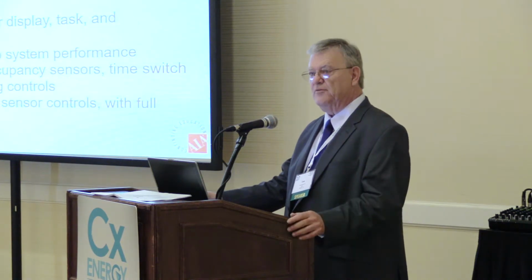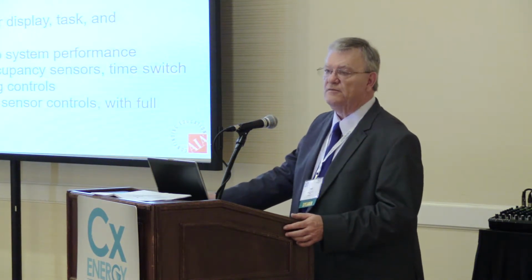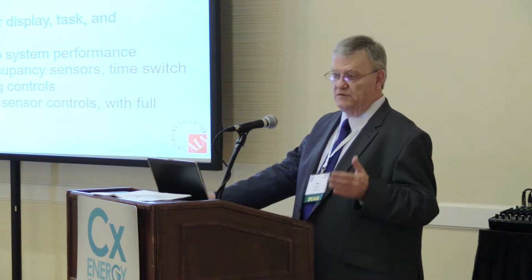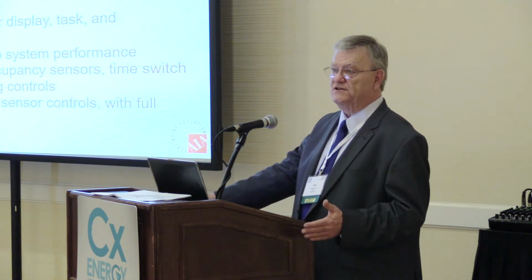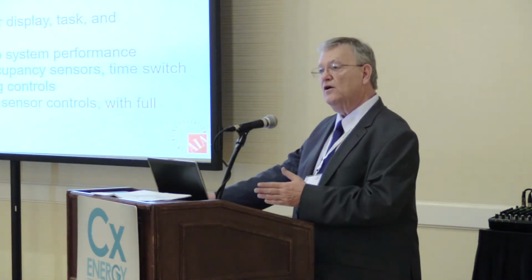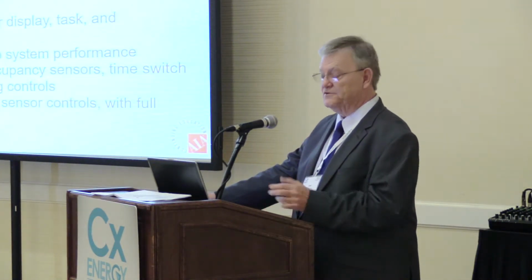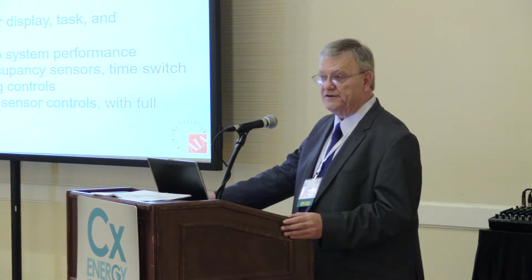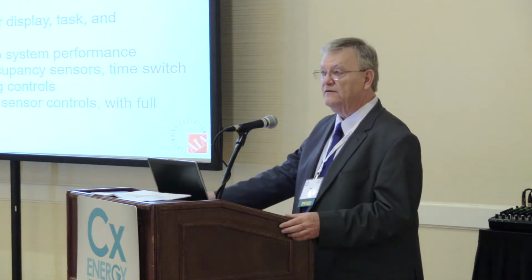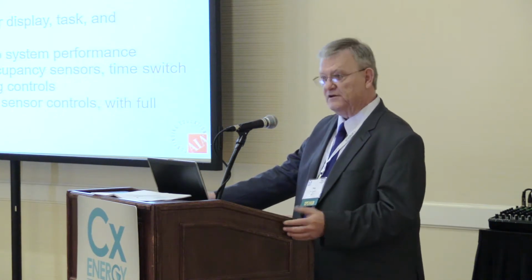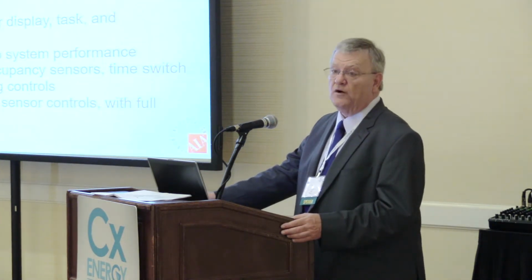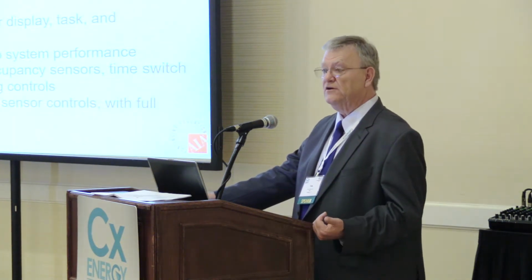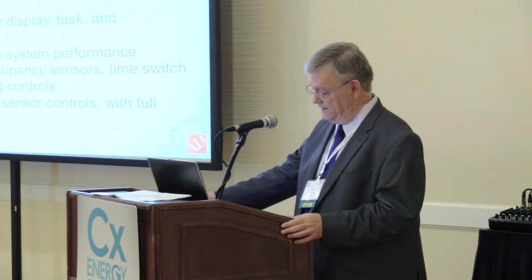Now, in the jurisdiction where I practice, they adopted this code in November last year. So we haven't seen a large building that was permitted under IECC 2015 go all the way to completion and look for a certificate of occupancy. So it's not clear at this time in Houston what form this will take. It might be something as simple as a ComCheck form, or it could be something a lot more complex. But the AHJ is going to be looking to me to provide some evidence of that, at least per the code.